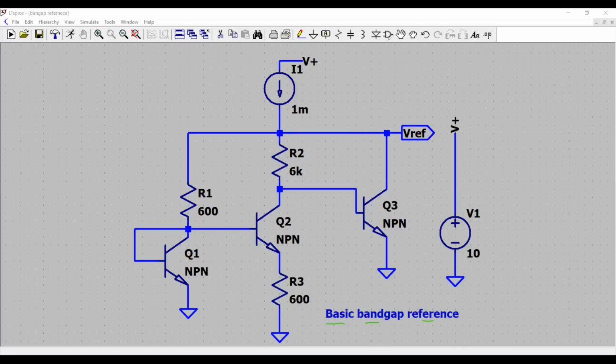So here is my component library. I picked up components such as Q1, which you can see is this diode connected transistor, and this is always going to be operating in the linear mode, that is the region right to this line here, so providing the constant current.